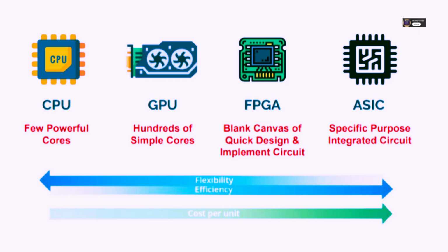And not just cost, right? Yeah, power and size, too. Definitely. It becomes the cheapest, the smallest, and the most power-efficient option per unit. You have to remember, FPGAs are inherently somewhat inefficient from a power and size perspective. All that reconfigurable logic fabric, even the parts you aren't actively using for your design, still take up physical space on the chip and consume some power.